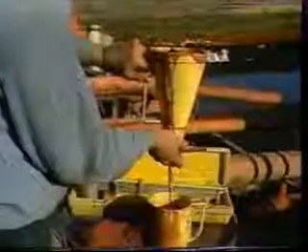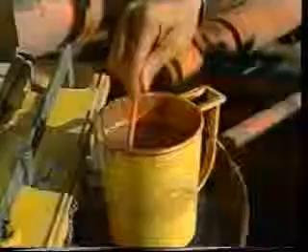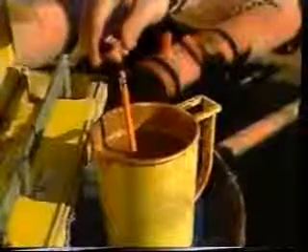These same clays also improve the drilling fluid's ability to transport the drilled rock cuttings to the surface, where they can be screened out and sampled for geological information. The fluid's viscosity permits it to carry these particles in suspension, and the clay increases the viscosity of the fluid. The clay also gives the fluid gel strength, a property which causes the mud to stiffen or gel when pumping stops, but allows it to liquefy again when pumping resumes. This property keeps the suspended cuttings from falling to the bottom of the hole when circulation is halted.